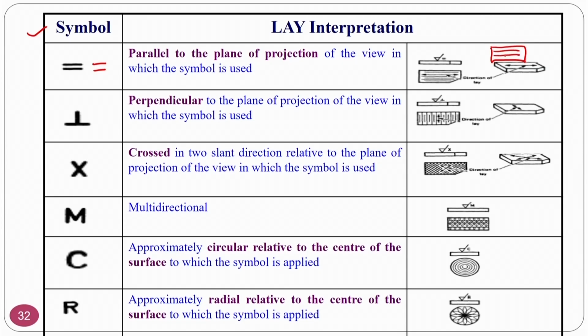Now you will get this type of surface pattern in a grinding operation at a particular location, because the grinding wheel rotates and it will generate, and your table moves to and fro, that is, the table reciprocates for that purpose. As a result, you will get a parallel surface along the direction of your table movement.